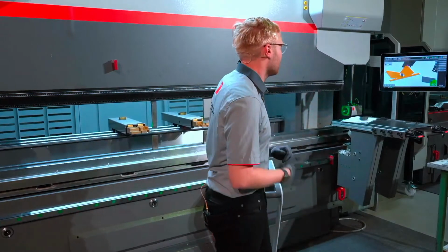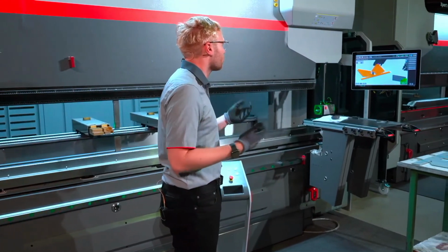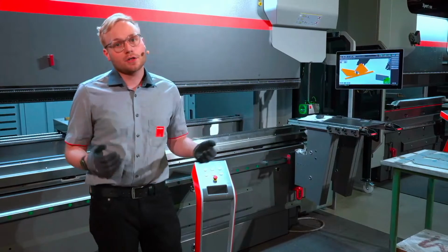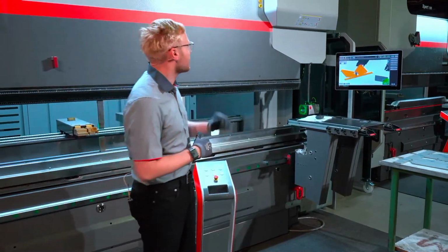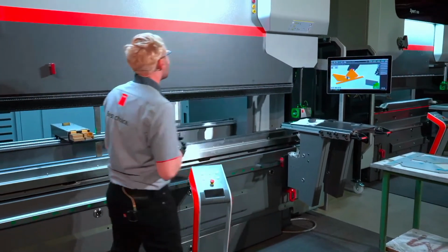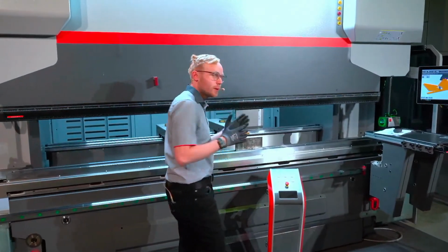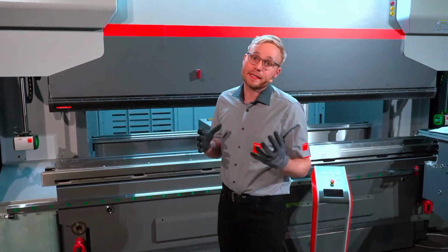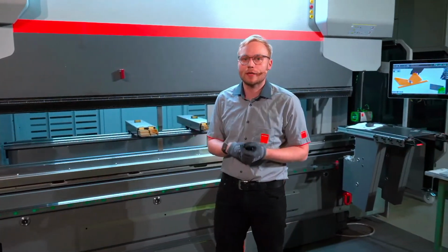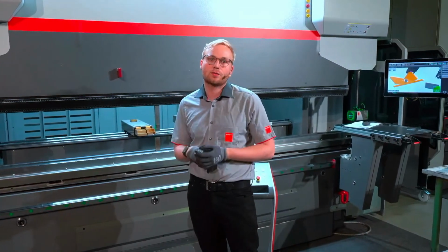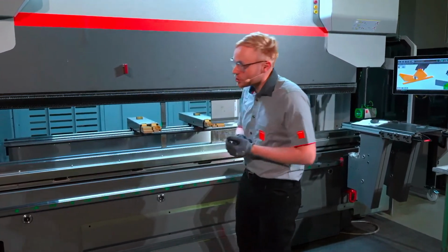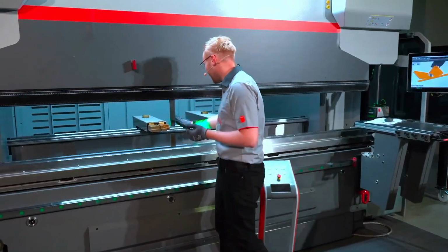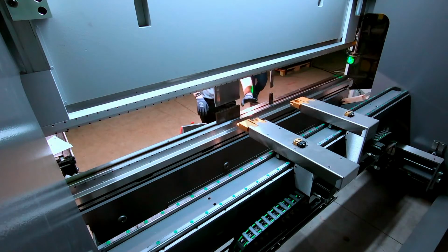It will automatically fit to the correct program tool height. We have the touchscreen on this machine to control everything using our software ByVision Bending. And we have the work lights. We have one in the front. We have another one in the back, which gives us the best lighting during the whole workday, so make sure that we have a good environment for working on the machine. Also, this machine is attached with our 5-axis back edge system, so we are able to move the right finger plus 150 to the front and also to the back.